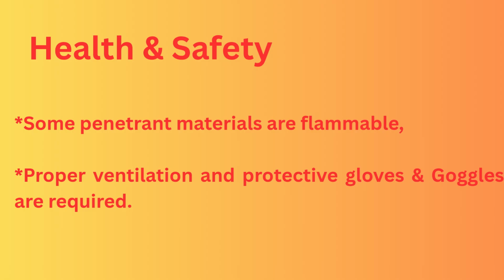Health and safety. Some penetrant materials are flammable, so use them carefully and store properly. Proper ventilation, protective gloves and safety goggles are required to perform a penetrant test.